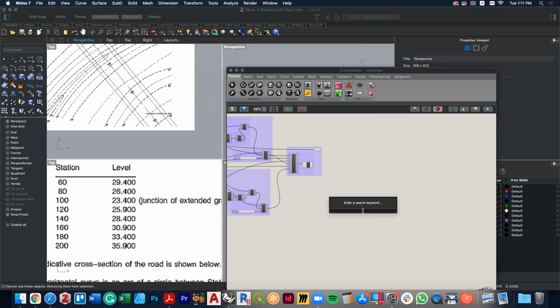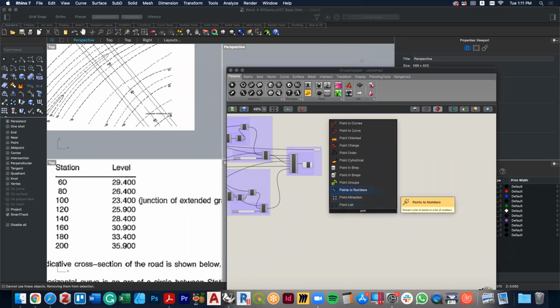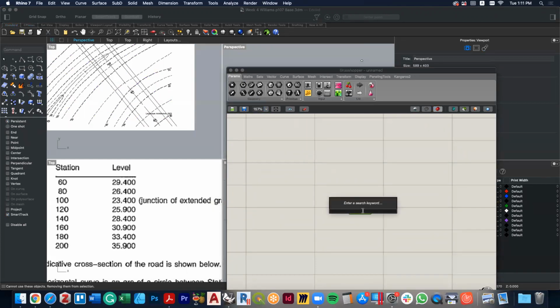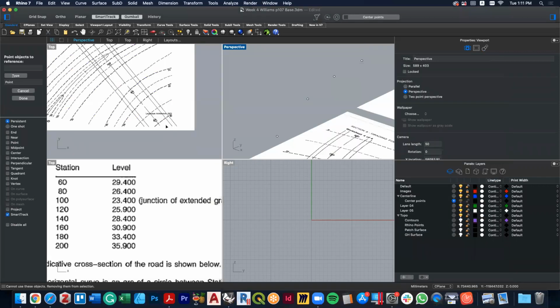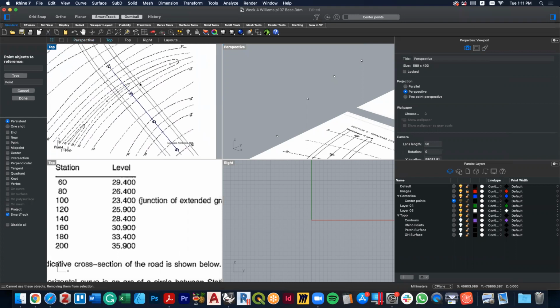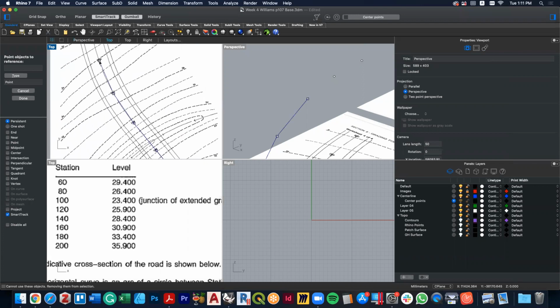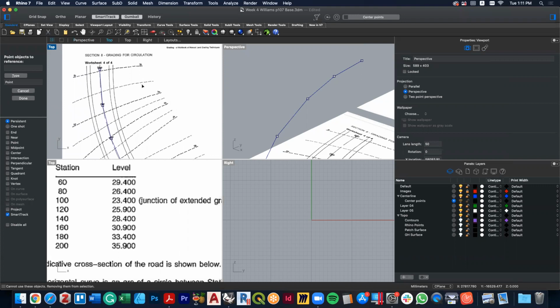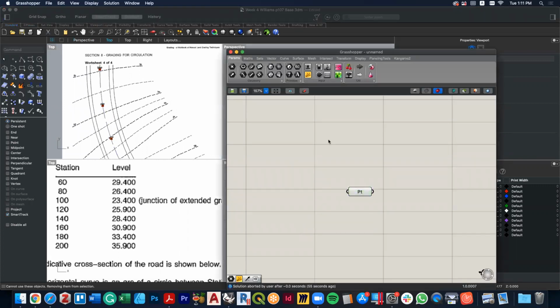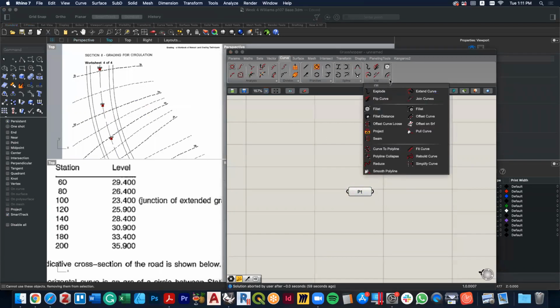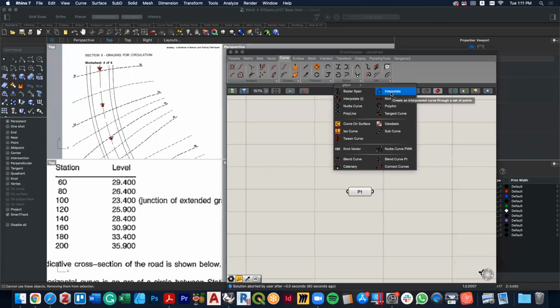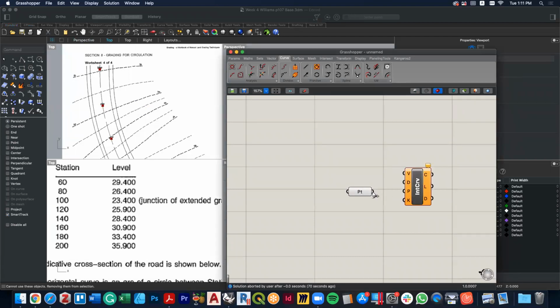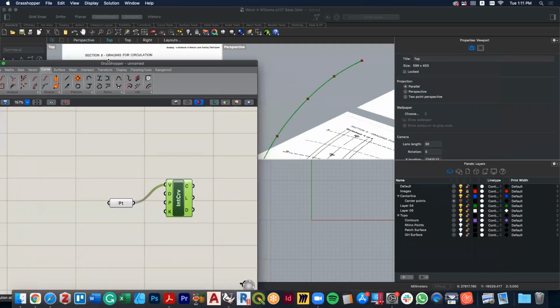And so what I'm going to do now again is choose point, and then right click, set multiple points. And I'm going to go along and very carefully choose the points in sequence. As I say, problems come when you start putting things out of sequence in this program. So I've got those there, and then I can use from curve. I can choose the option that is actually under spline, choose interpolate, and if I put them in, you'll see that I end up with that curve there.